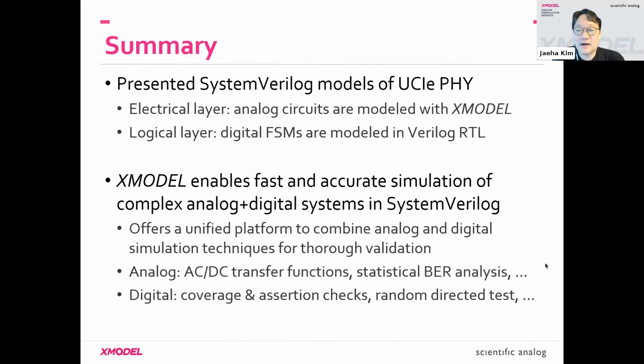It is also theoretically possible to model the power delivery network, but I did give you a heads up warning that every time you make the models more complex, it's going to have impacts on your simulation speed. So it is possible. Simultaneous switching noise is actually done by some of the people. But power delivery network is a very, very difficult problem. If you have a massive RC mesh describing a power delivery network, and you want to see every single voltage on each node, that's going to be a daunting task.